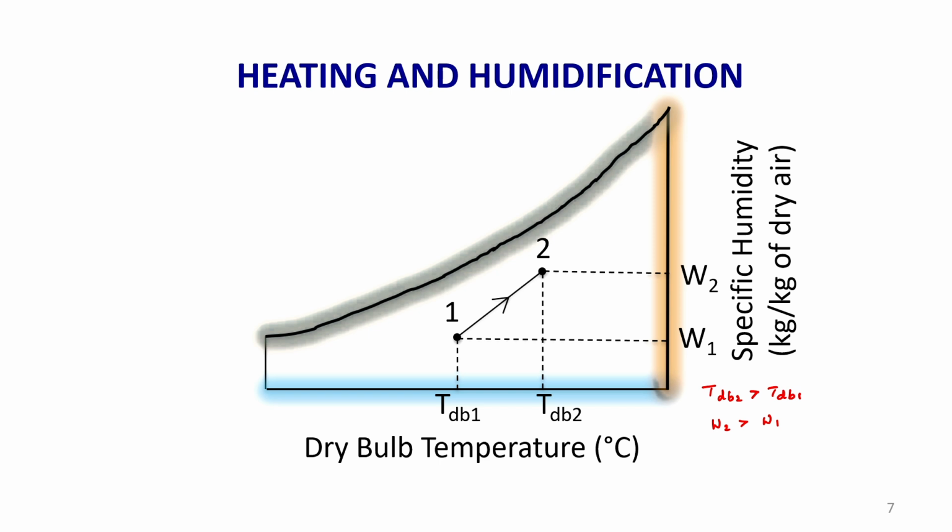When we say expansion, it will also be pointed towards state point 2, but in the downward direction. So, compression is always expressed with the arrow mark in the upward direction. The expansion process arrow marks represent the downward direction. Similarly here, when I say heating, it is an inclined curve pointed in the upward direction.